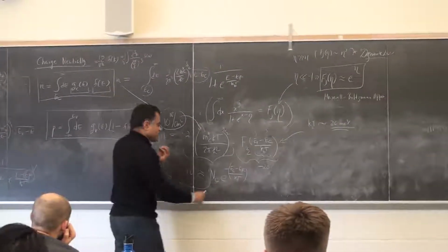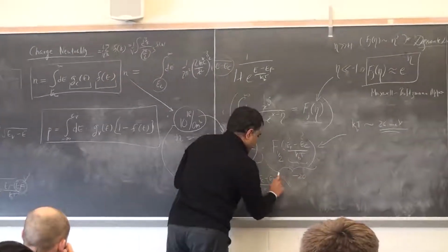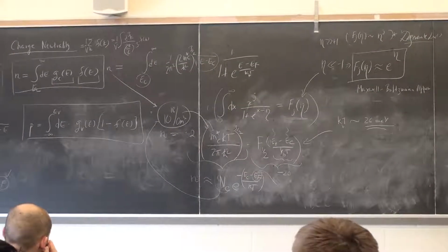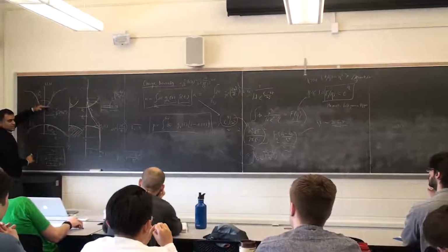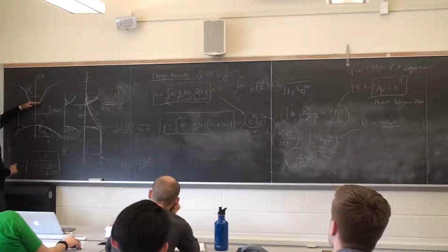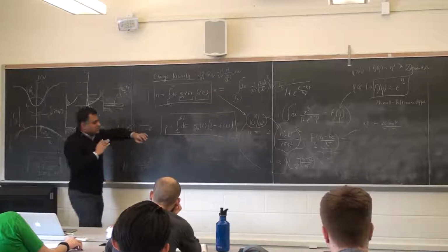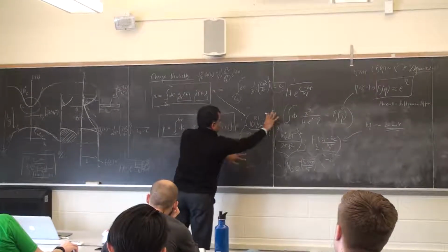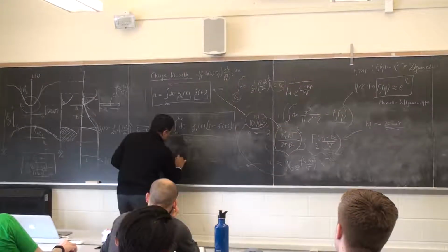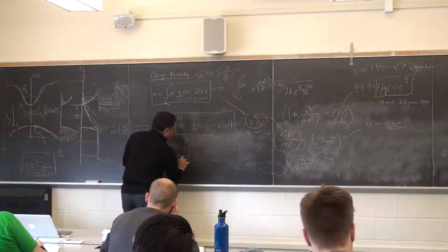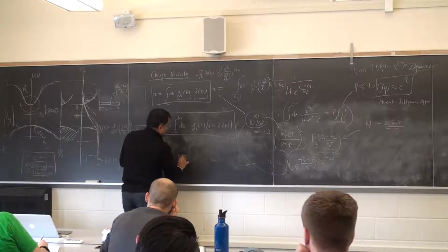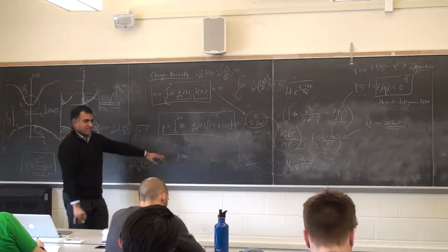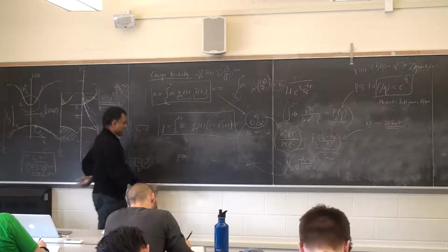Later on, we are going to see this Fermi level. We will control it in a transistor, for example. We'll control the Fermi level location with a gate voltage. So that's how we can populate or depopulate the states externally through a third contact. In the exact same way, what we did here, you can find the hole density. I'm writing approximate, but many times if you open a semiconductor devices book, you'll see it written as equal, but it's understood that this is an approximation, and I showed you the approximation.